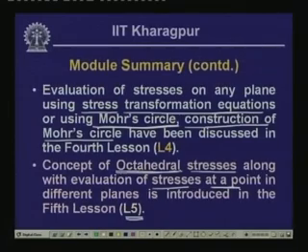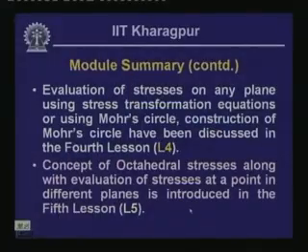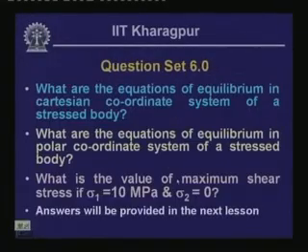As I have told you, the octahedral stresses are the stresses which act on octahedral planes, which are equally inclined with reference to the principal axis system, and these stresses are useful when we talk about the evaluation of stress in the inelastic stage. And in this particular lesson, we gave you the concept of the stresses in a polar coordinate system that you have already looked into.